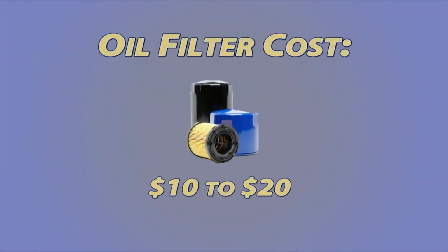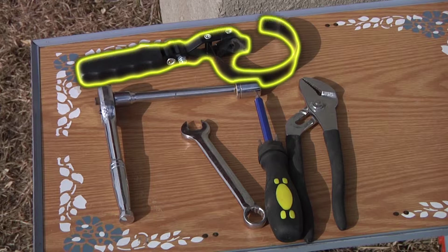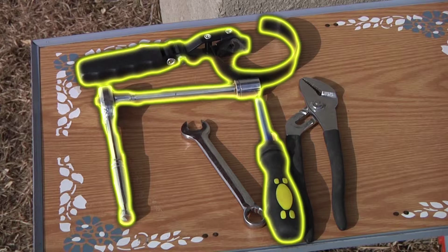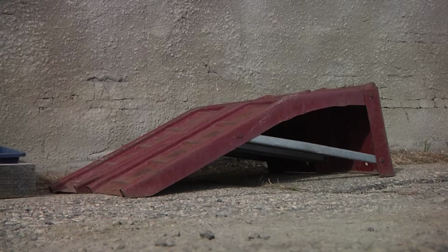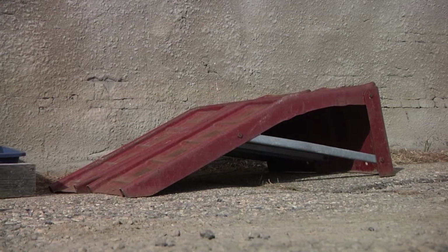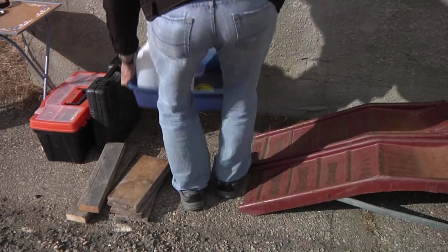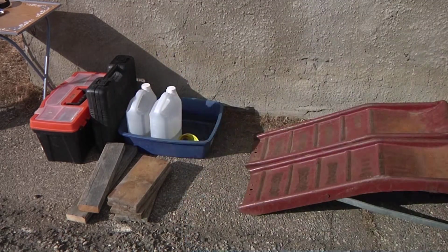You'll also need a new oil filter. The average price of one runs about $10 to $20. The oil filter I purchased ran me about $8. The tools we'll need are a proper sized oil filter wrench, proper sized screwdriver, and a proper sized socket, or open-end wrench. Ramps will be needed to mount the vehicle on, so we can get underneath. Wheel blocks are encouraged, so the vehicle won't roll off the ramps. We'll also need a catch container to catch all the oil that falls out, and a proper container to dispose of the old oil for later.